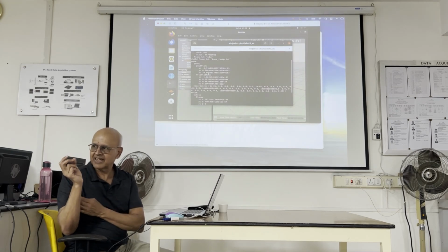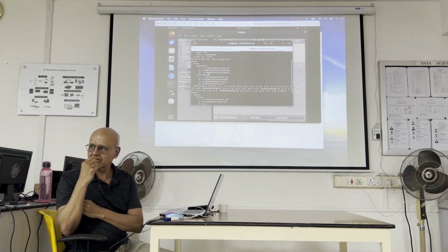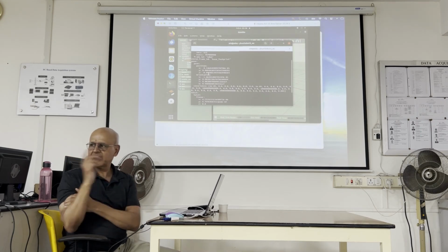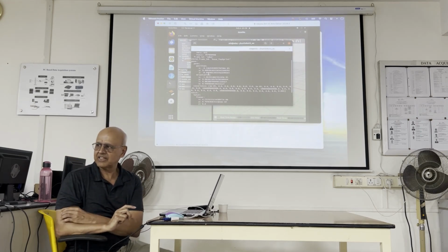You had a question? So it says odom does not appear to be published yet. Did you launch Gazebo? No, you should launch Gazebo. So ROS core is not there. Okay, can you open another terminal window and say ROS topic list?